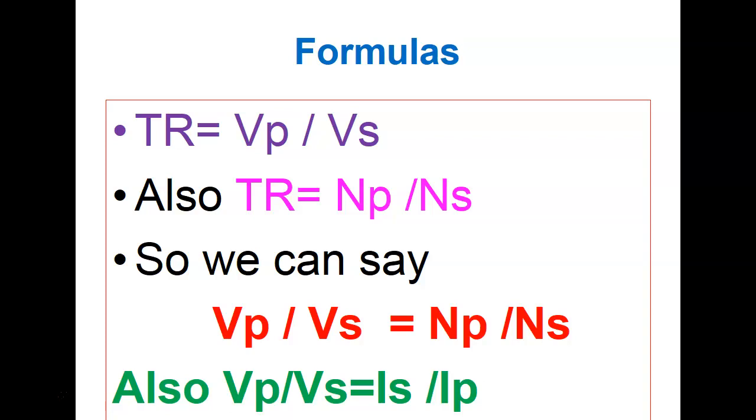So AC, when you come over here, you have these 2 transformer windings. This guy's putting out a positive. This guy's getting a negative. What do the windings want to do? They want to move toward each other, right? You understand? And the windings, positive, want to pull together. So this is why transformers hum. Transformers hum because the windings are constantly trying to do what? Move in and out with each other.